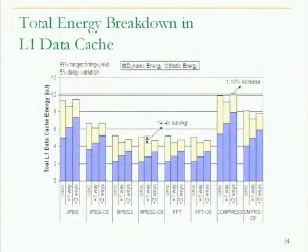So in a four-way cache, you have to do 4 comparisons per access. But in instruction cache, you do not really need to do that, because most of the time the next instruction is in the same cache line that you accessed before. So in that case, you can skip tag comparisons. If you do that, you get the results that I showed you here. But in data cache, you cannot do this. For every cache access, you have to compare all the 4 or 5 cache tags.